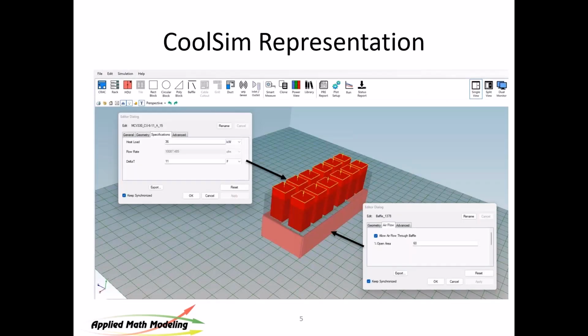The way we represent these in CoolSim is we've generalized the PDU. We used to have a PDU little entity or object up here. We called it a PD, power distribution unit, and we use that inside the room usually. Now the room's gotten much bigger, and we're going to use it outside. The room is effectively the domain now. You're setting the domain, sometimes called a bounding box, for the volume that you're going to put your building in.